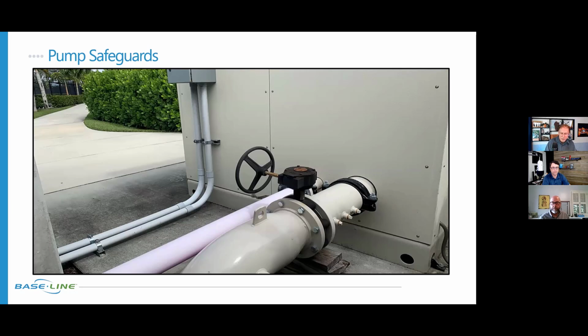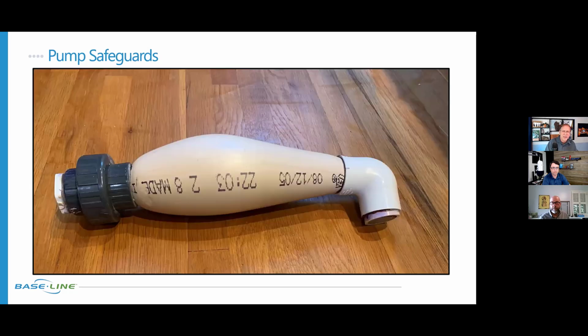And on those old systems, it's really easy to deadhead a pump, so pump against a closed gate valve. And this is something that is very real. I picked this up when I worked distribution. This is a 1.25-inch pipe, and they were pumping against a closed gate valve right after that union. They pumped against it all night, and that 1.25-inch pipe swelled up to at least 3 inches, and it's paper thin. And I really have to credit the person that went to shut this off, because that was incredibly brave, right? That was ready to burst.